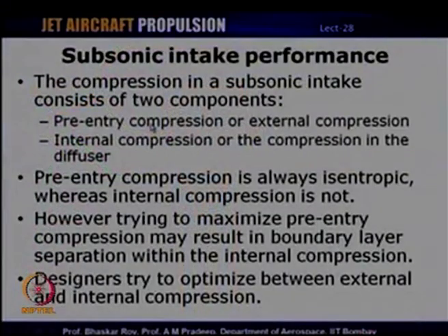During takeoff, in fact, there could be a pre-entry acceleration taking place, and so that does not really contribute towards the overall pressure rise taking place in the intake. And so, under these two operating conditions, we will now see what really happens within the intake and how we can evaluate the pressure rise under these two circumstances, that is, pre-entry compression and the internal compression. So, compression in a subsonic intake consists of two components, as I said.